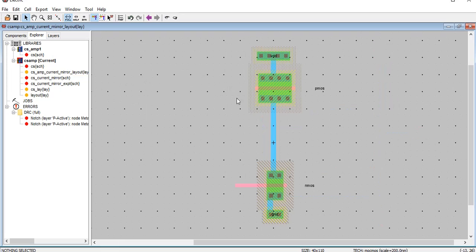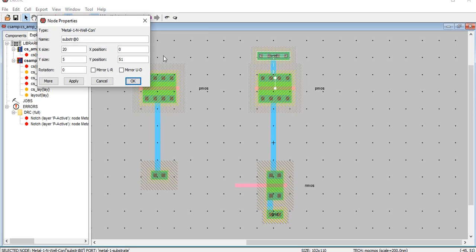So, I have already a PMOS. So, let us take this entire thing and I'll Control C and Control V, I will place it, no issues. And this VDD portion I will delete it for time being, because I can connect this entire same portion to this VDD. So, what I will do is I will just enlarge this X size from 30 to 50.